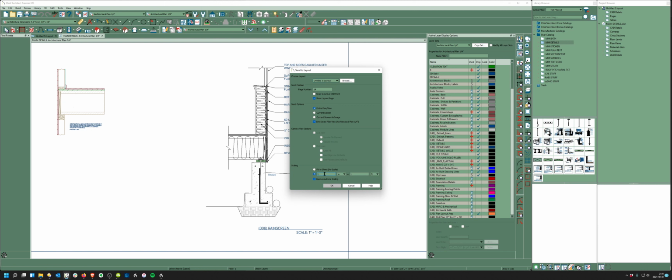So first I'm going to change that to 1. I don't want the entire plan view because that's going to grab everything you just saw when it opened. I want the current screen, and it's going to go to page 14, which is page 14 on this untitled, because we were there. So the trick is go to the page you want to have this thing export to, and then when you go to export, it's going to default to there. So let's hit OK.